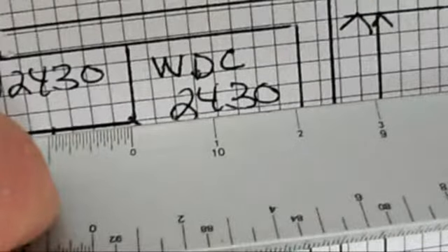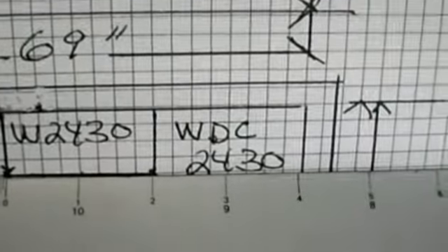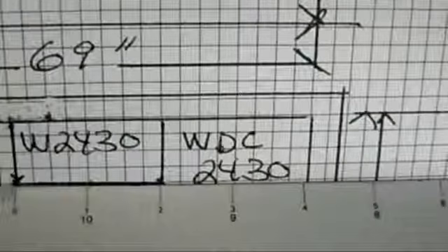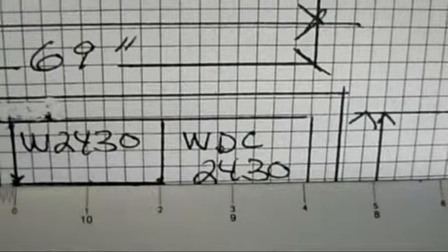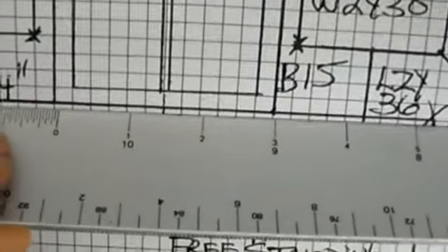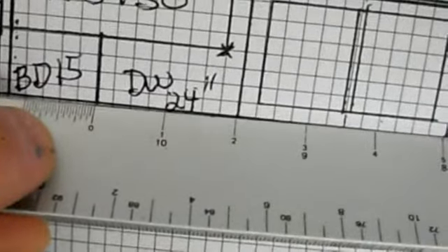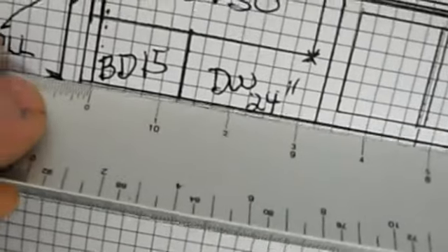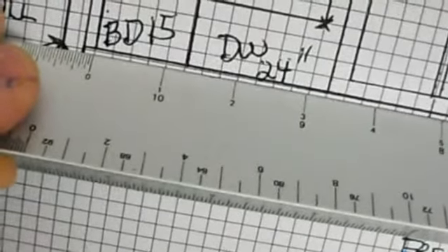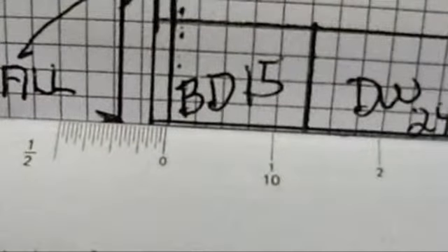You never know. Your drawing, you might need a spacer on each side of a sink. Remember, fillers are your friends. There's nothing wrong with using a spacer if you need to. Yep, there's my notation on the 1-inch filler. That's that little blotch there, but it is there. There's our 36-inch sink cabinet. There's our 24-inch dishwasher. And then there's our 15-inch base cabinet, and then again the spacers. You'll notice on the wall cabinet just above the dishwasher I have the little X hash mark. That's just a little reference line that I use to make sure that everything is parallel and lined up. There again is my spacer.